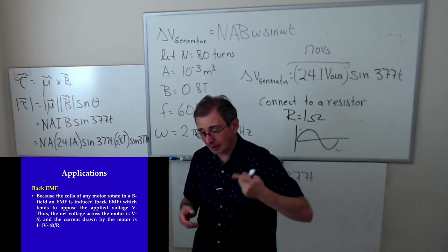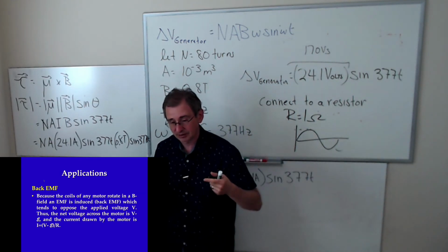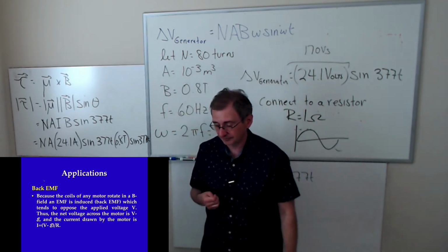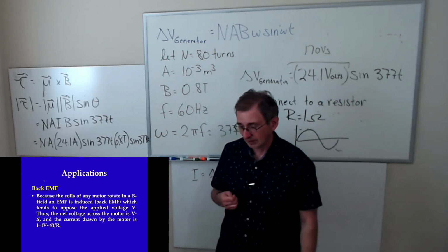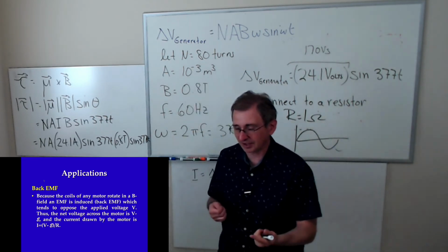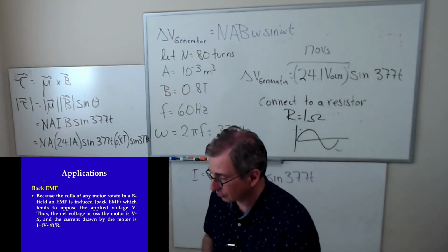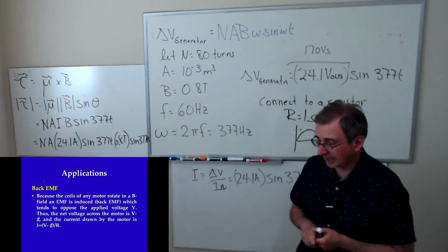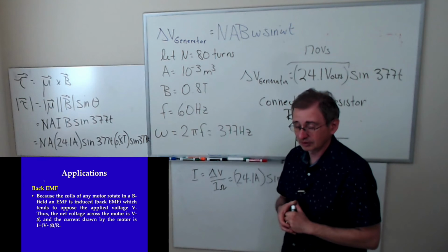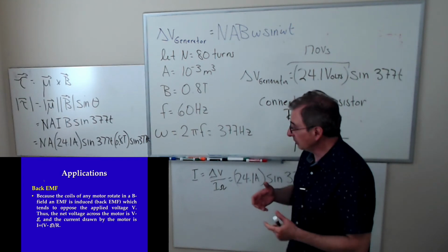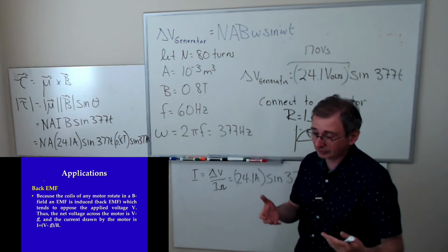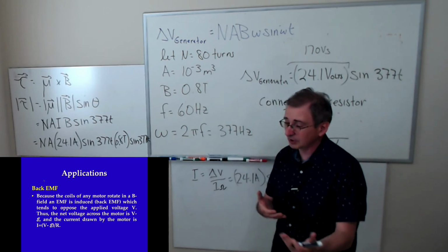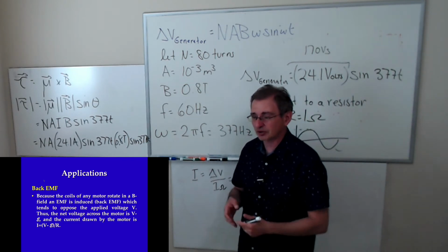And so when the motor is operating at its maximum speed, the back EMF causes it to draw less current. In fact, motors want to be spinning at their operating speed so that they draw less current. And this effect is due to Faraday's law. Because in a motor, you do have a loop of wire rotating in a magnetic field. The flux is changing. So therefore, there must be an induced EMF in that motor.